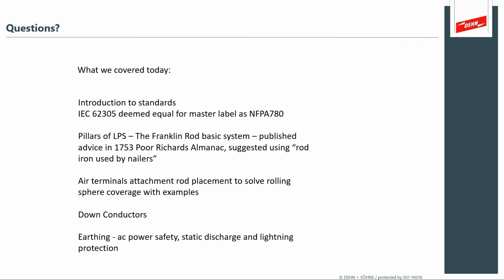We're saying that it has to be that distance away from any other metallic conductors or grounded metallic bodies, anywhere where lightning will flash over and be conducted into the structure to cause damage. So the separation distance calculation does not mean it can't be installed within that distance on a wall or anything. It just means that I don't want to have that flash over to any metallic grounded metal bodies. I don't know if you want to add something.